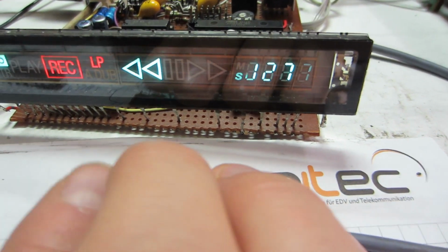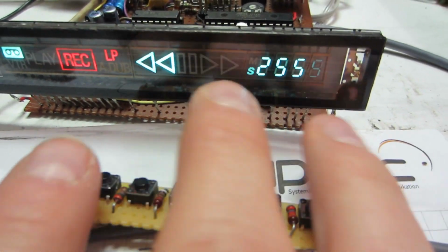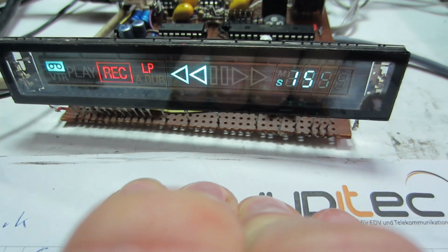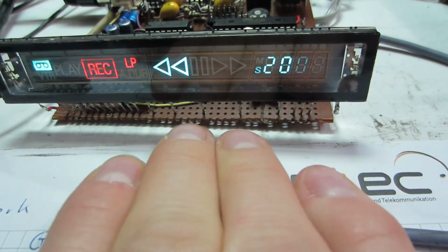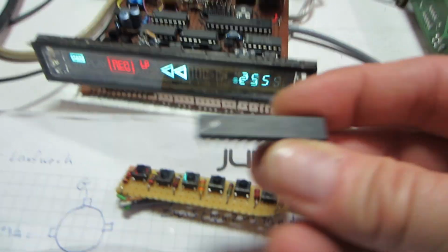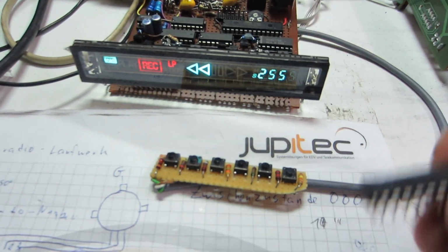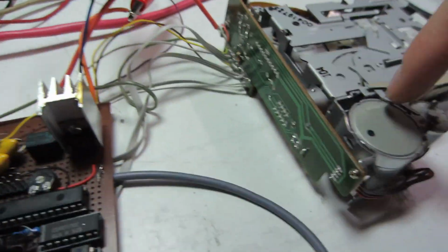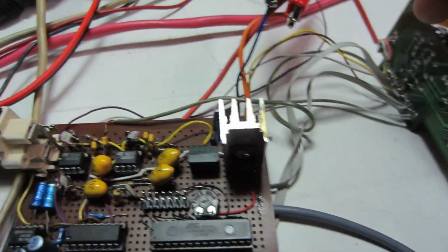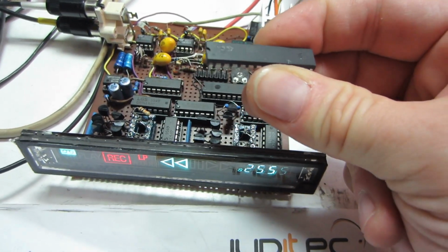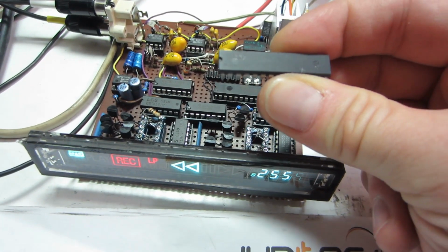So the 8 bits of the microcontroller, 7 of which are hooked up to each of those single segments. If you press several at the same time, you can get funky values. By the way, this is the chip, and this is one of the reasons why I stopped developing for this. Look at how janky that is. One of the capstan motor control broke off and shorted to the 12 volts, breaking this IC. It's not dead, it's just write protected now.